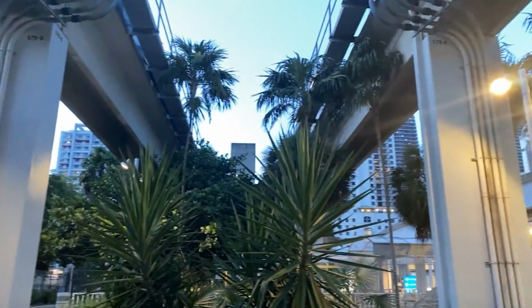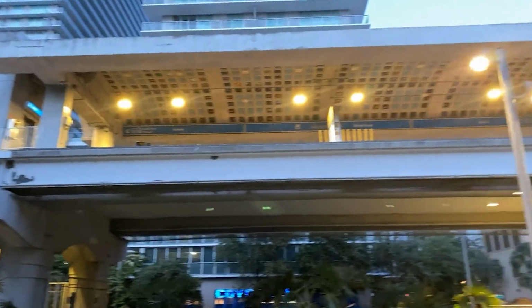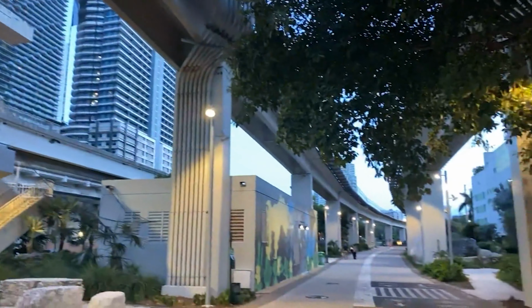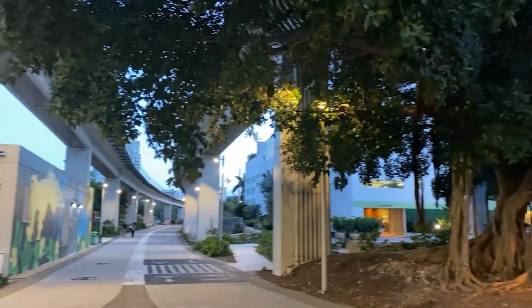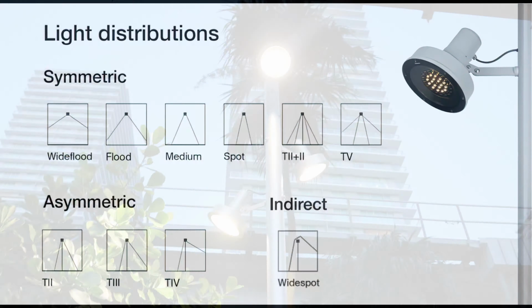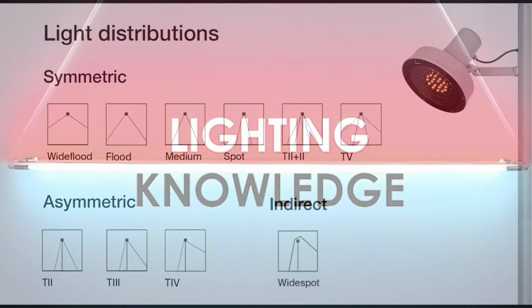One of the key elements for having good lighting design in parks is uniformity. People feel safe in places with uniform light. For reaching this goal, we need the right position of the luminaires and select the correct beam angles. ARNE luminaires have different beam angles related to their lighting distribution. They could be symmetric, asymmetric, and indirect.